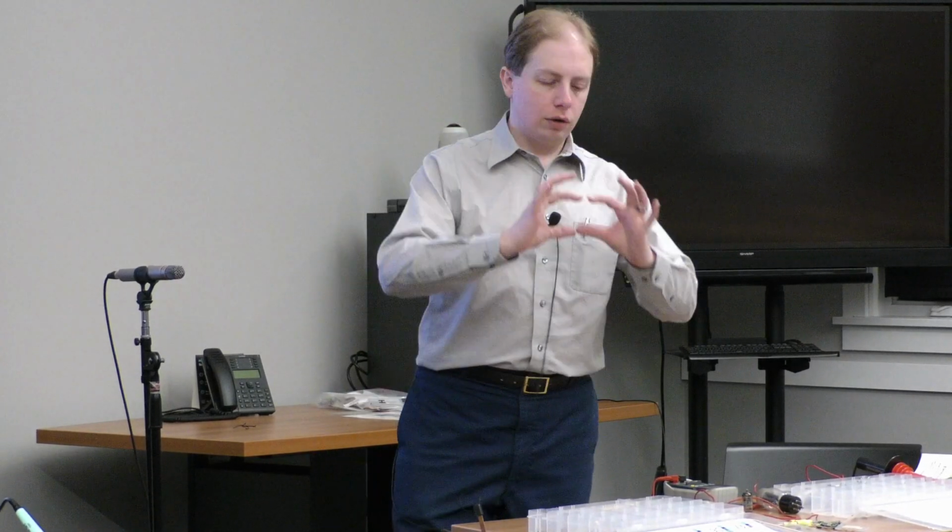Your book will tell you what the symbols are, but there's a lot of basic ones that you need to know. And from a practical standpoint, you can just go online and look them up. I will also say that there are different standards for symbols, especially US versus international standards. Like the book shows a little rectangular box for a fuse, but internationally, that usually represents a resistor. But once you look at a schematic long enough, you can usually tell what's what.